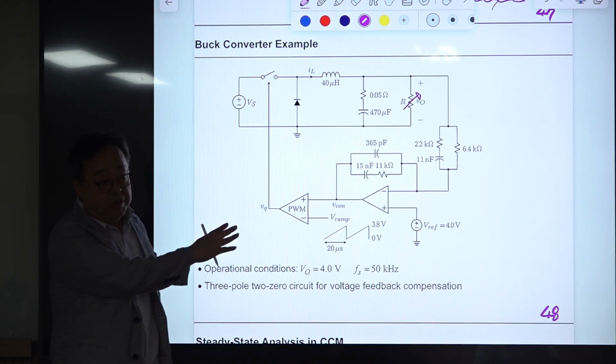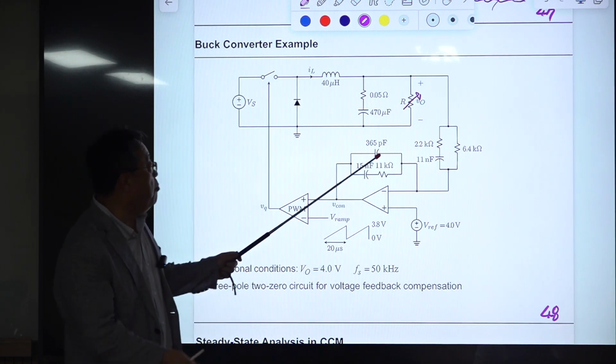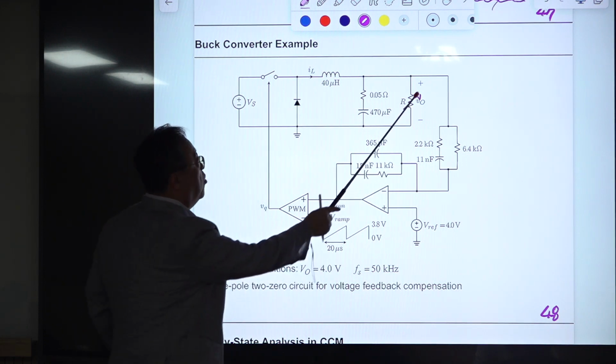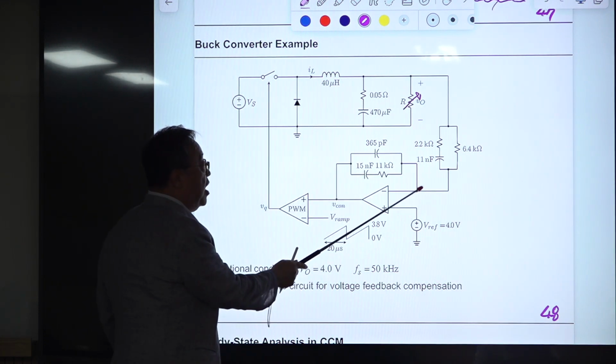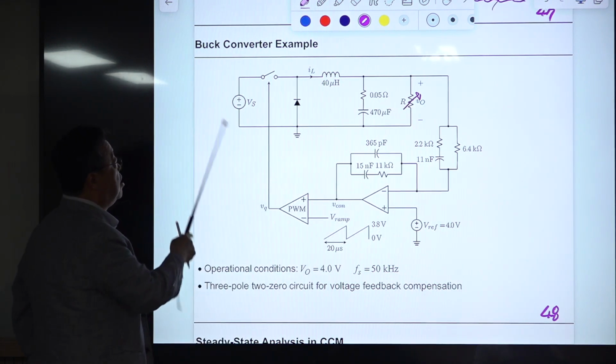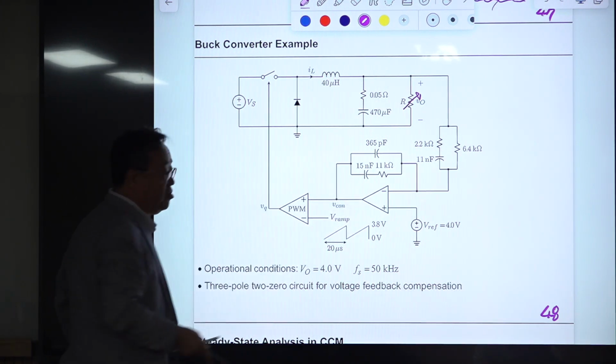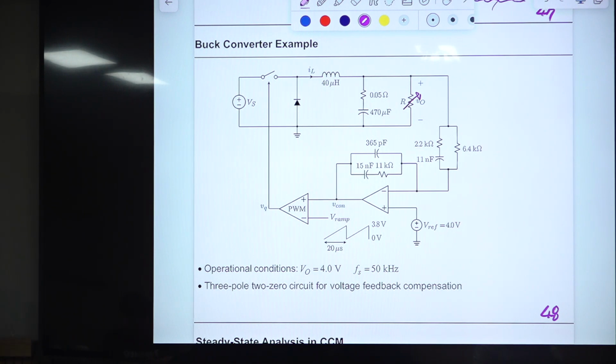So in some transient response, this converter will go to DCM mode. Still, this output voltage is regulated at this value regardless of the operational mode, because we have this structure which satisfies the requirement for DC regulation. The input voltage will be varied, and we will be observing this inductor current, output voltage and control voltage.